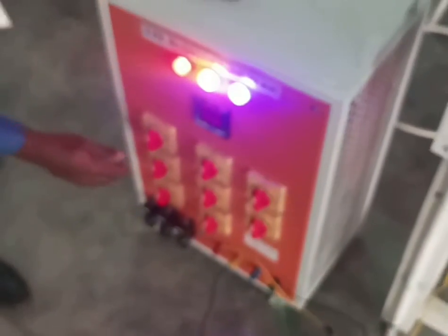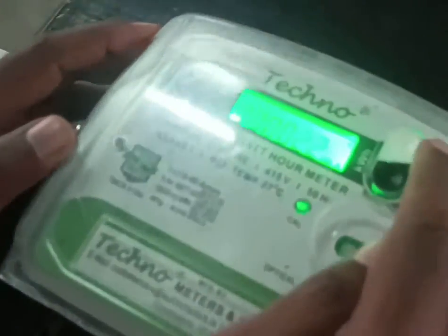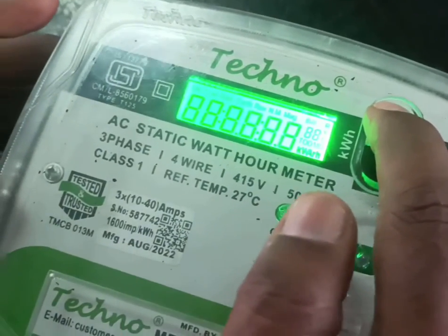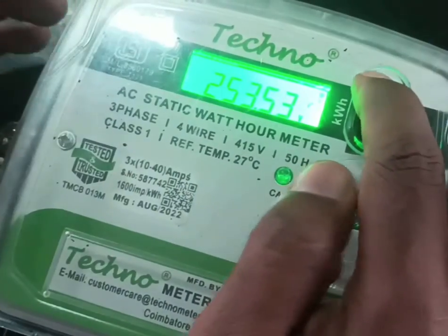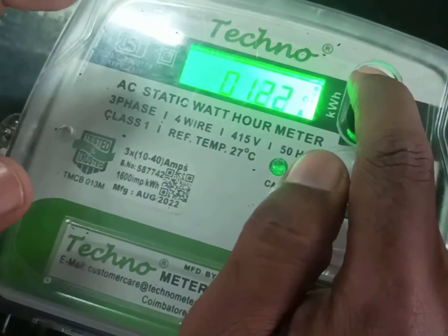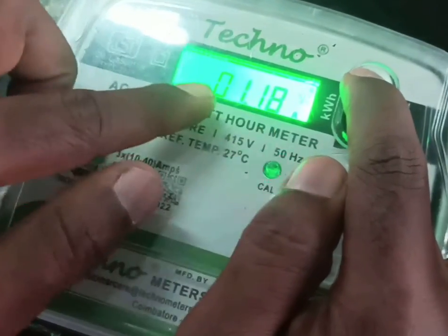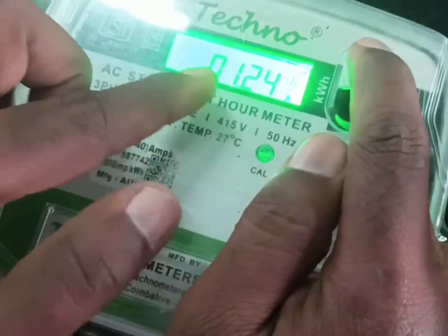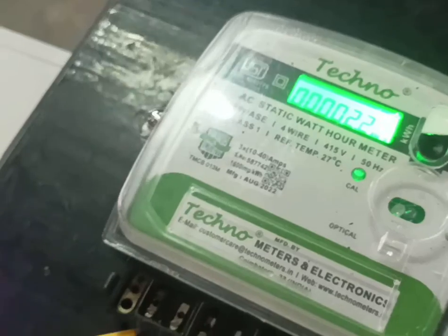Now I am going to switch on one load. The load is now on. Let us check the same. If you check the voltage level, this is the R voltage 253, Y voltage 243, then B voltage 252. Now the current becomes 1.22 A on R. This is the current 1.18 A on Y. This is the current 1.24 A on B. So if your load is on, the current increases. As per your connections, the experiment is verified.